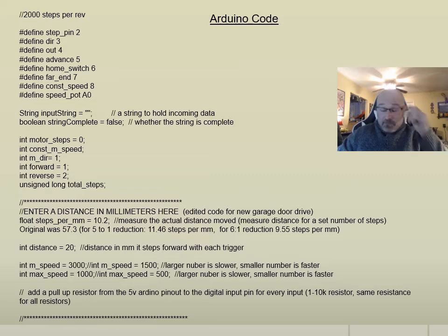As we physically build the system out and go from that initial block diagram and concept up through a physical connection of all the hardware in our black box area, what we really need to spend a lot of the time on is programming and coding it out. We chose to do this on a simple Arduino. It's not a lot of computing power that we need for this project. We really just are talking to our sensors to get that feedback control of our motors. So a simple Arduino and a motor controller is really all we need for our electronics. It's low power consumption, low cost, and a little bit easier to program.